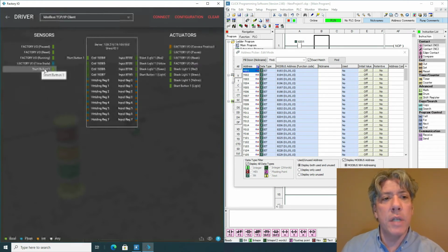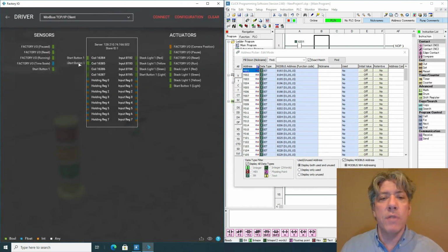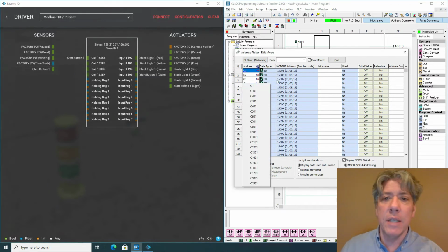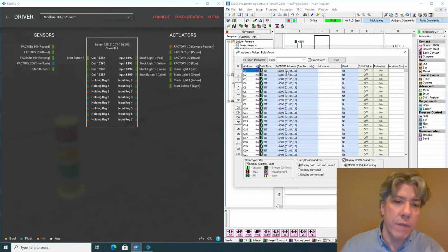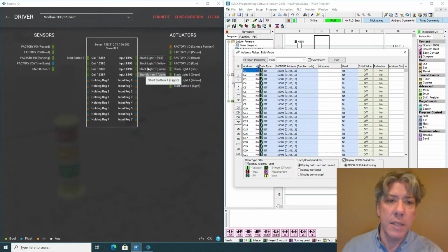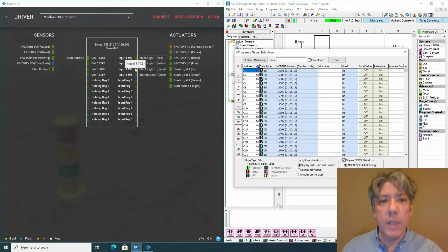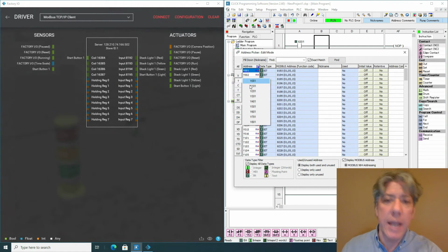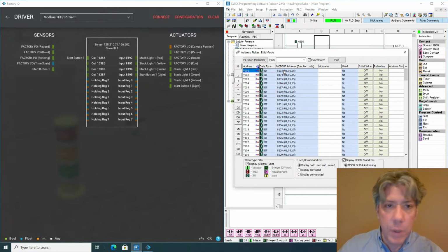The way I did that was I dragged it over, and it's like wiring. Basically, I've taken that push button switch and I have wired it into the PLC, going to Modbus address 16384. Well, not exactly, right? I mean, in the PLC, Automation Direct calls that 16385. Remember the 1 address or the 1 unit offset there. So the start button's wired in here, and then the stack lights and start button lights I have wired in to address 8192 through 8195. Remember, I'm using actual outputs for this, and they start at 8193, but I've got to go to 8192. Why that is, it doesn't matter. I don't know. It doesn't matter.